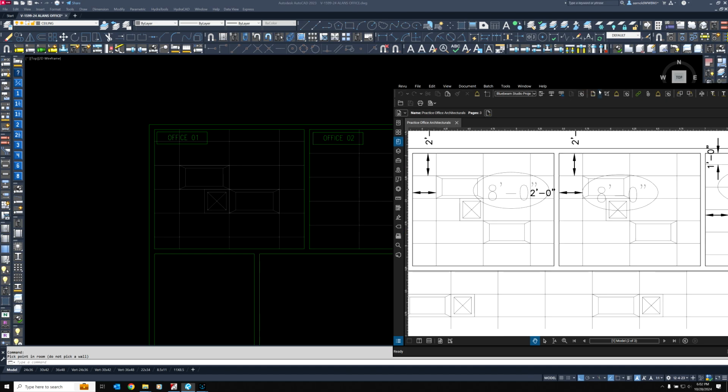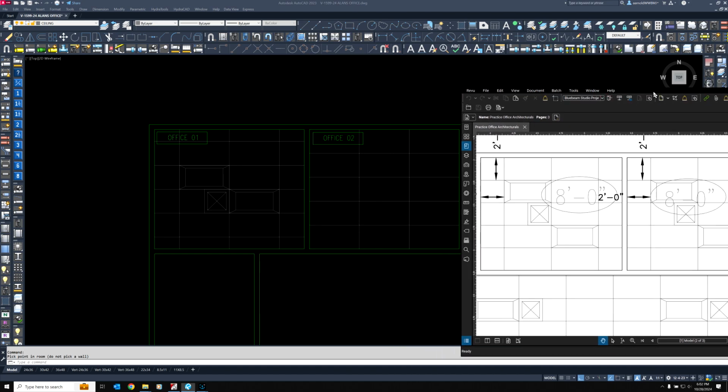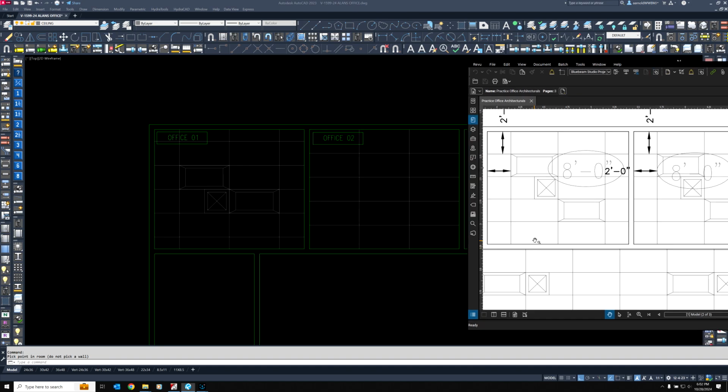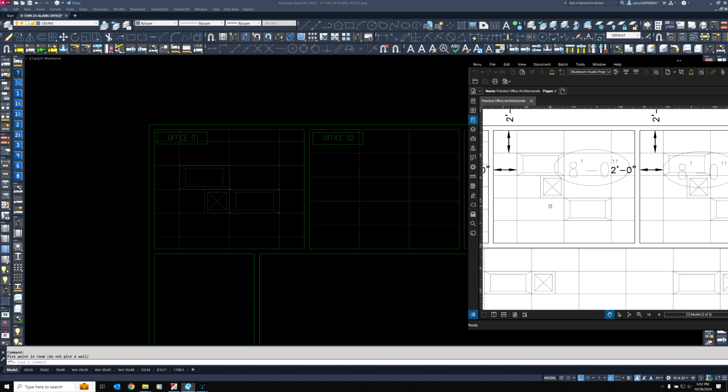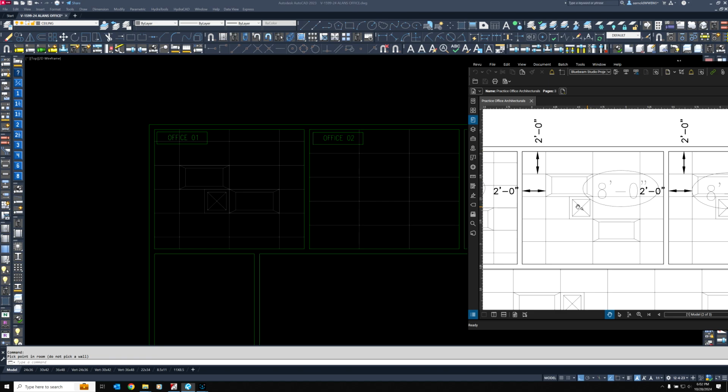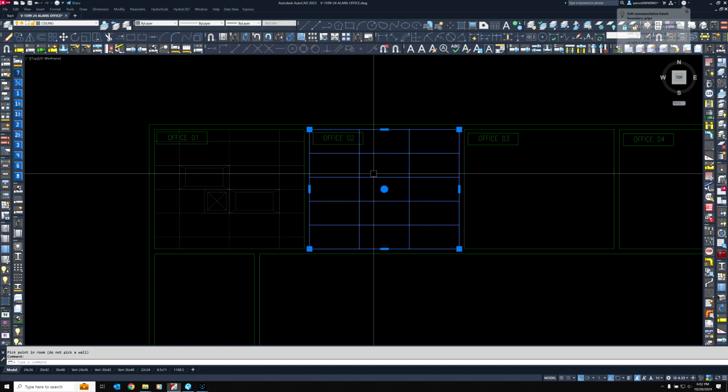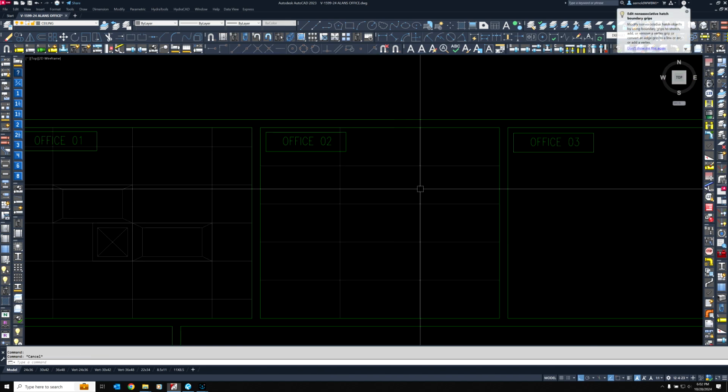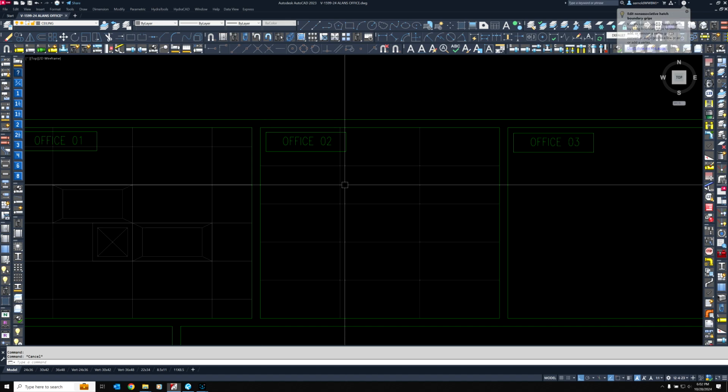If I could keep these side by side large enough. Oh my. Your T-bars going left and right line up. Your T-bars going north and south do not. You have 3 whole ceiling tiles in here. You do not have 3 whole tiles in this drawing. It's got to look like this, obviously. So we know that we're 2 foot by 2 foot in this version. This one, we should be able to count on this being a full 4 feet.